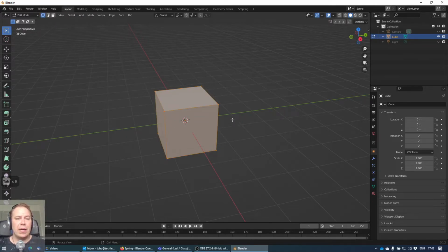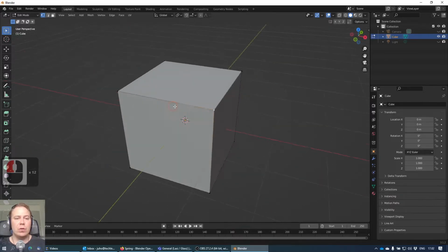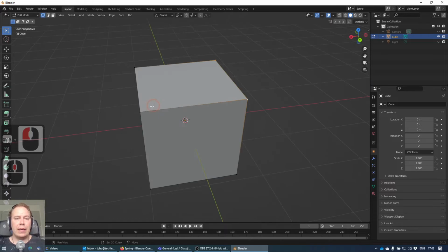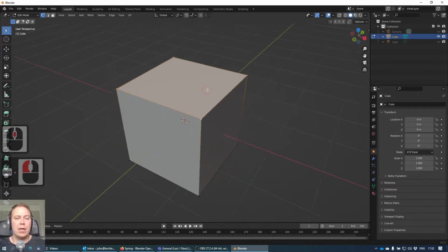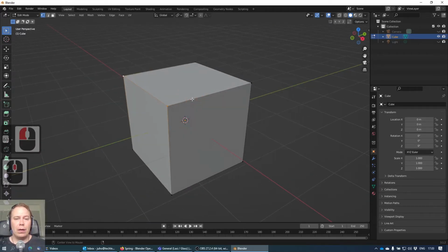So basically the 3D modeling mode is the edit mode, and here you add all the modifiers and so on. In edit mode you can access these vertices. So if you go to edit mode, you can select these vertices individually. You can select multiple vertices by shift clicking, or you can select the whole line, the whole circle of vertices, by clicking with Alt.